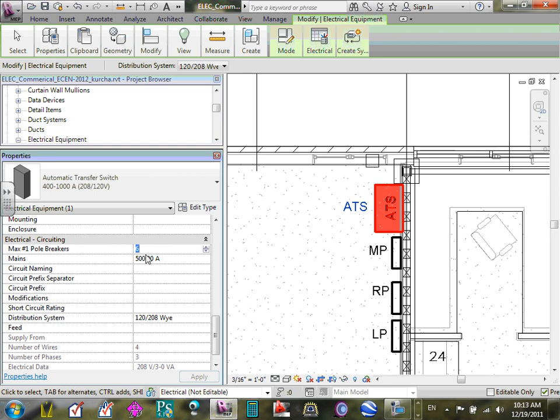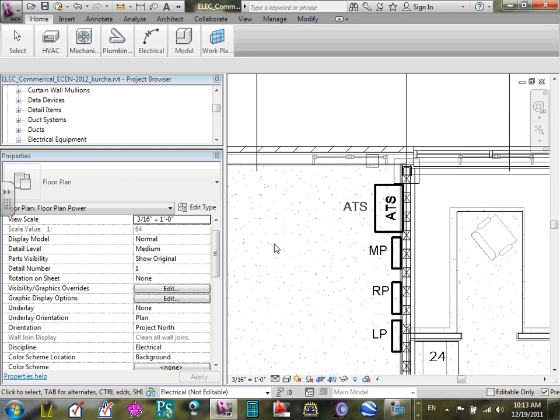Okay. Do me a favor, just change the maximum number of poles to 6. Maximum number of pole breakers: 6, so that will give you 2 circuits coming to it. I don't know really what this would do in a circuit breaker, but just put it 6. Why 6? Because I have 3 going to the 3-pole, 3-phase going to the utility, and 1 going to the transformer. That's why I came up with 6. But I don't know what's going to play here. Okay, everybody change this info, guys. So done. You have your auto transfer switch ready to kick butts.